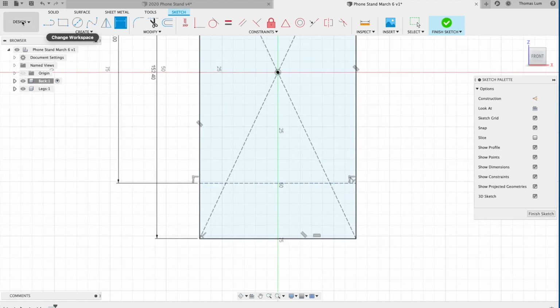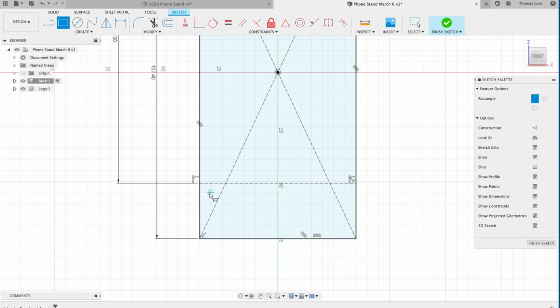All right, so now let's put in some rectangles. I need 3 rectangles here. They're all going to be 10 millimeters wide, but the height of them is going to be that thickness parameter that I put in before. So I go 2-point rectangle, just kind of start one. I go right up, and notice it snaps to that construction line. I'm going to pull out a rectangle here. The height is being asked for first, so I'll just type in THI. That'll bring up the thickness. Notice it actually recognizes it. I need to click it so that way it knows.